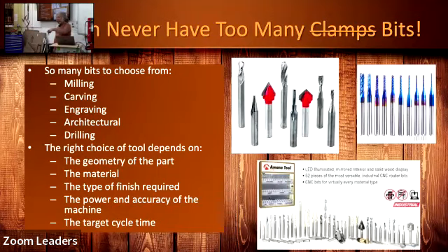If you're going to be drilling in, you want an up spiral bit because the up spiral clears the chips out of the hole. On the other hand, it makes a mess out of the bottom if you actually go through. So there you'd want a down spiral. Anyway, there's some of that.